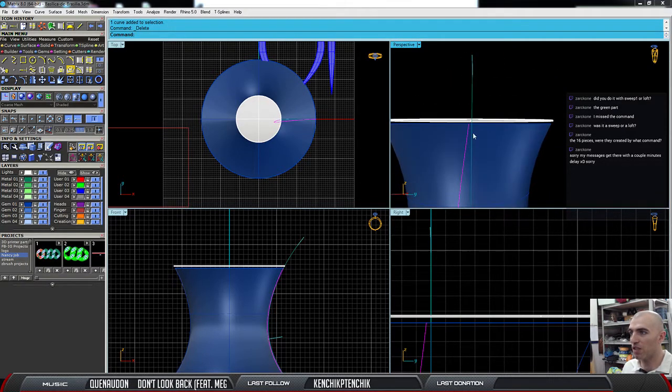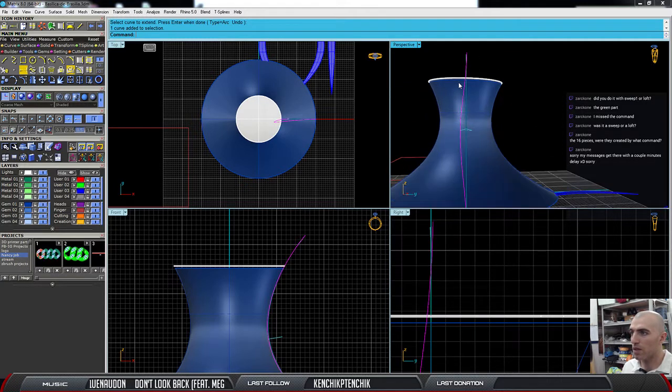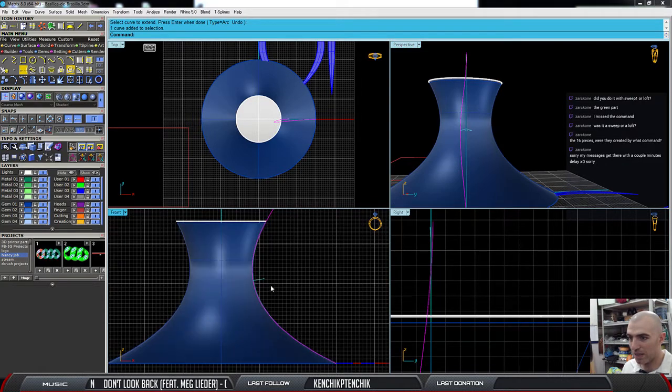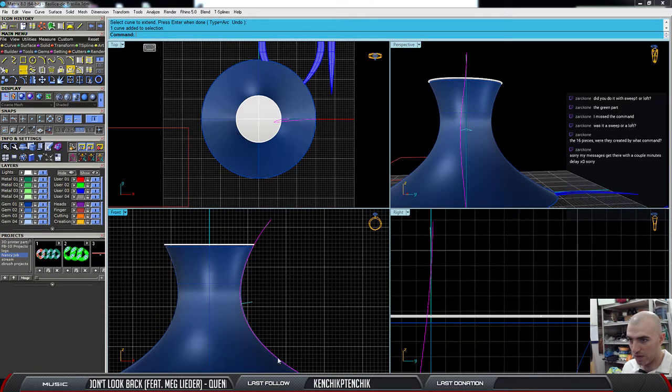Because when it projects here, there is no surface, so it will not do anything regarding that. It will just cut from the edge. So what I will do again is extend all the way up. Up, wherever, here it will be good. Okay. So now I have this curve matching exactly the surface.